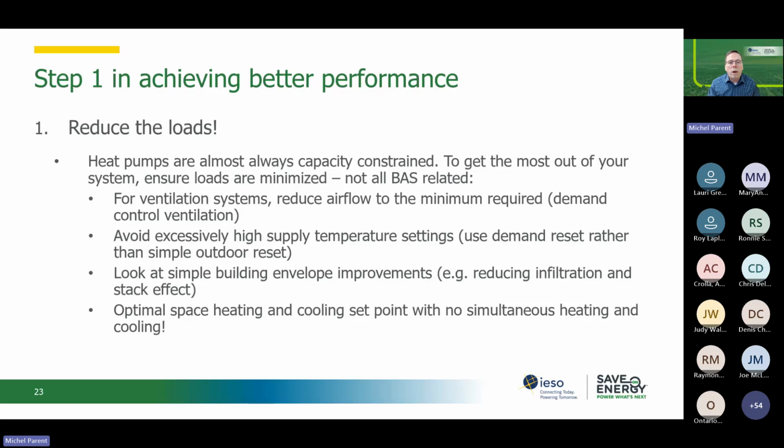So you've got to be very careful about minimizing as much as possible both space temperature, and do not ever compromise comfort. So I'm not saying put the temperature in the space at 18 degrees. That's a mistake, but don't allow 24, 25, 26 degrees in heating unless for some obvious reason it's mandatory in your building to have that.